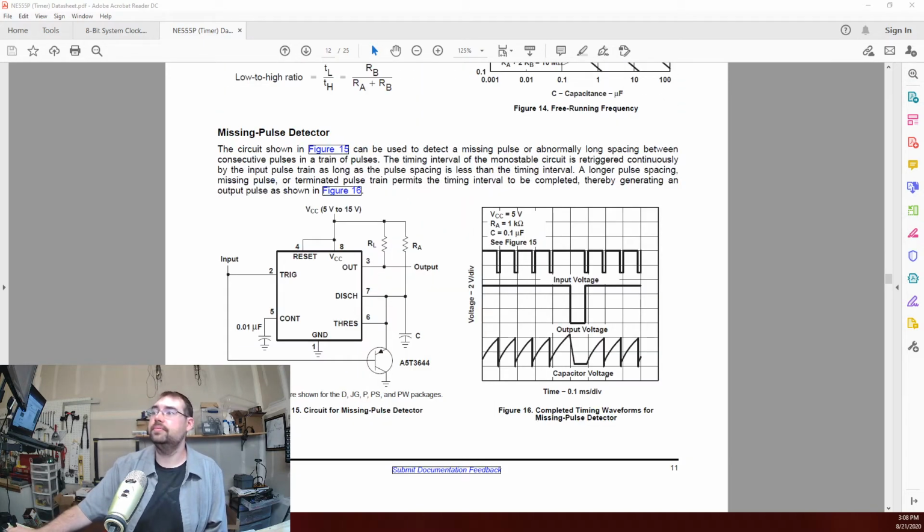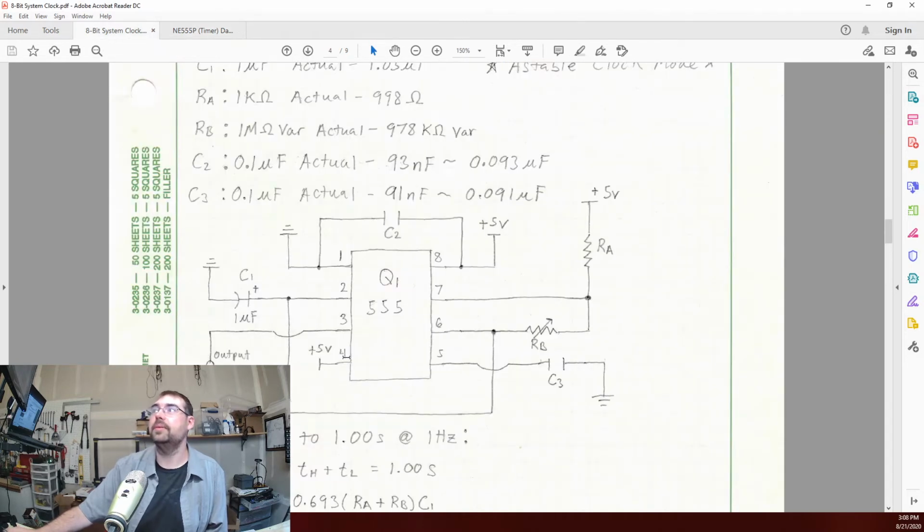Anyways, put that back up there for us. So for capacitor 1, C1, on our schematic, we have a 1 microfarad polar capacitor. Capacitors C2 and C3, what were they? They were 0.1 microfarad capacitors, so 1 times 10 to the negative 7 farads of capacitance. They're just enough to keep everything kind of clean.